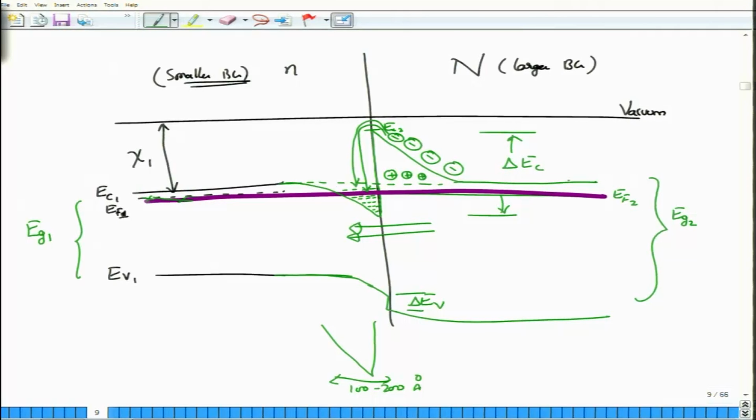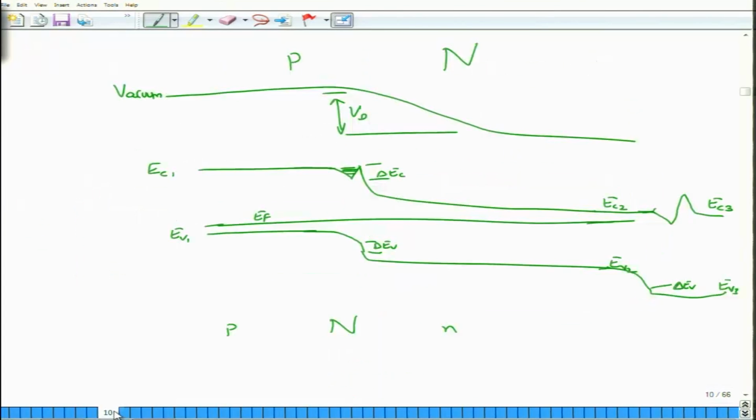So, as you go from the small n, first it will encounter a well and then it goes back up. So, this is actually correct, sorry, for multiple reasons. So, this is how this layer would go. Okay. Of course, these spikes are not going to be constant when you bias it, when you actually apply bias to the junction. So, this was a P N and a small n junction. Okay. This is not normally used, but we will come back to the actual one that is used in practice, but this is the idea.